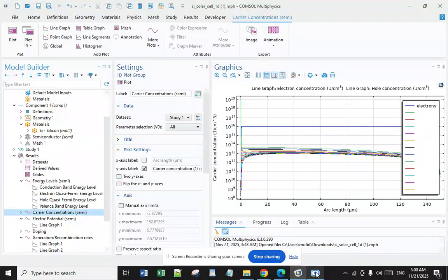We can also investigate the Shockley-Read-Hall recombination rate and user-defined photogeneration rate for the entire cell's thickness. The semilog plot below shows that, as expected, the user-defined expression for a single exponential function is a straight line.